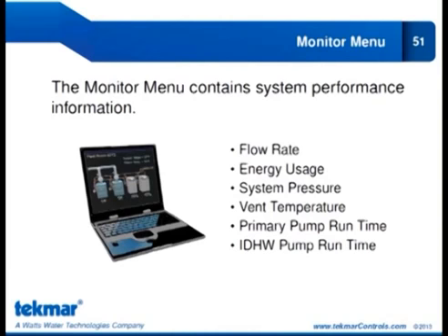Then we can also use, and this is kind of nice for an ECM pump, because let's just say we're activating an ECM pump, and that's your system pump, or sorry, your primary pump. It could be an Alpha pump, it could be a Stratus pump, and we do know that with those, if those are your primary pumps, it's very hard to prove flow. You can't take a standard paddle or anything like that, because sometimes you have problems tripping that.